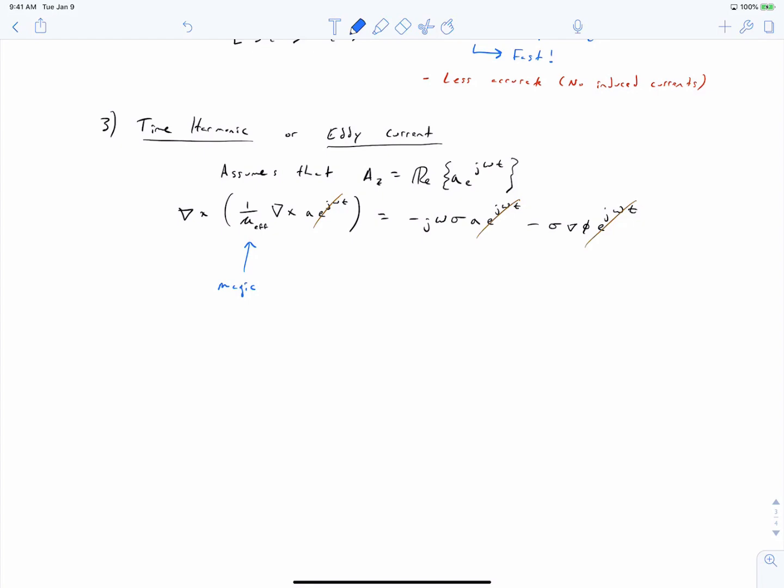The second thing I want to point out is that this equation that we have up here is intended to solve our solution at a specific frequency of omega. So if we want to sweep the frequency, if we want to evaluate our solution at different frequencies, we have to do a bunch of separate solves for each value of omega. And so we can say that this solution approach looks static for any given frequency. It's a steady state solution.